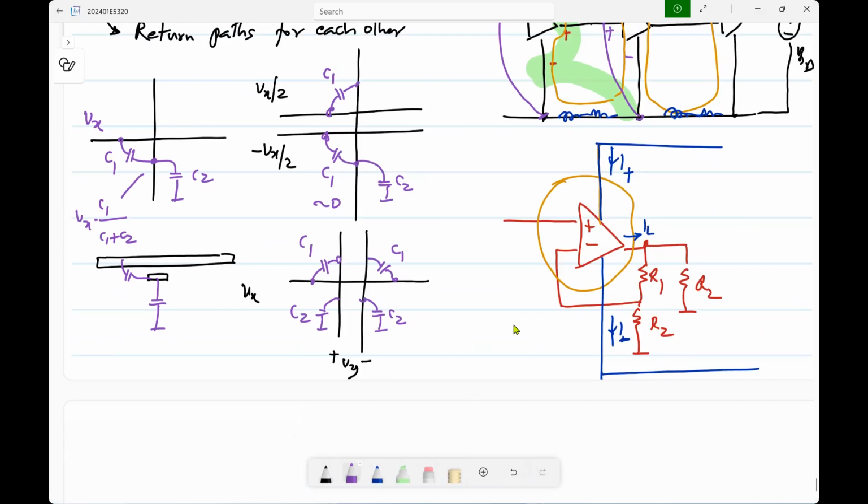The only thing is, of course, that you have to use fully symmetrical circuits. It's almost like doubling the number of wires and so on. On an integrated circuit, it doesn't matter. What matters is the total area, not the number of components. On a discrete board, it may be the opposite, because the number of components will increase the cost.